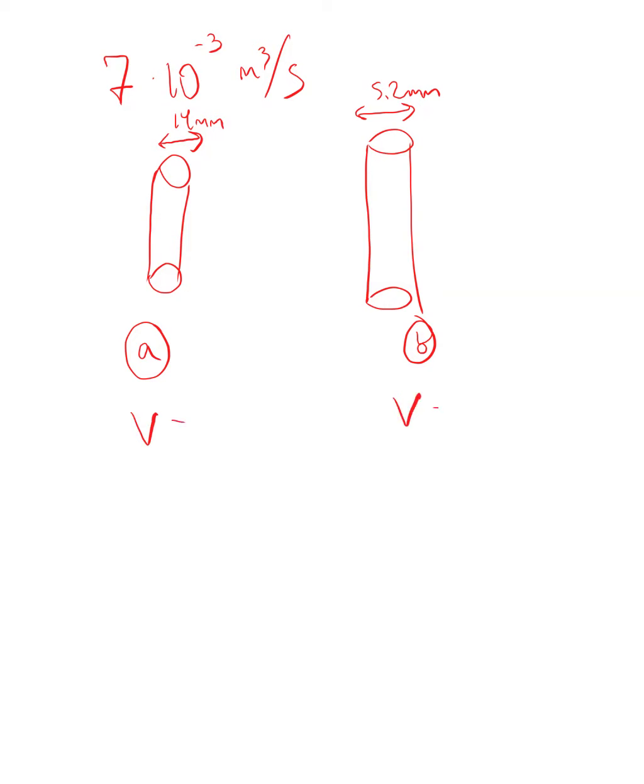And if you think about this, my expectation is that since I have a wider pipe here for the air to go through, and a narrower pipe here, I would expect this number, let me call this velocity B, to be higher than velocity A. So when I solve this problem, I will look at the numbers, and if VB is more than VA, I'm happy. If it's not the case, then I will go back and look for a mistake.